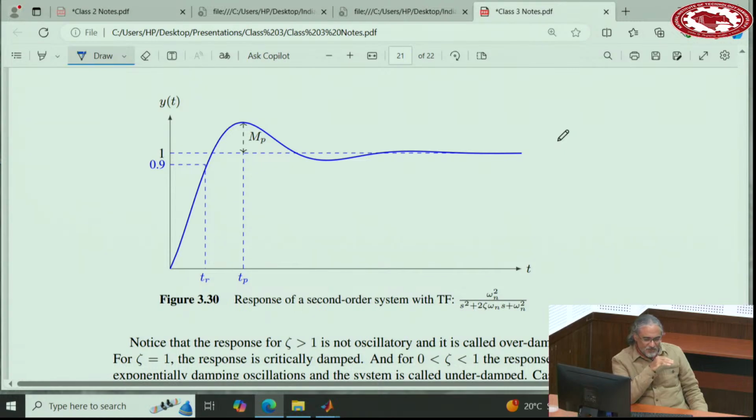In other words, it has an oscillation and it has a rise time or settling time. And you can imagine these things are in trade-off. If you try to make it faster, by reducing the time constant or reducing the settling time, your oscillations may grow larger.